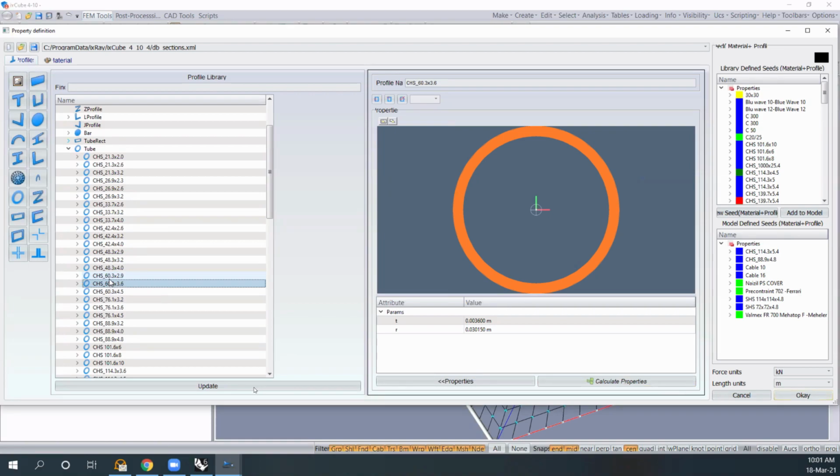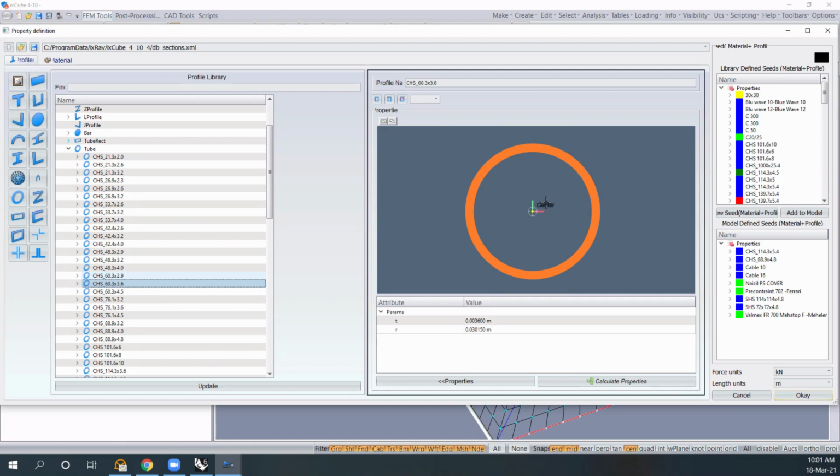when we run structural analysis on a tensile structure, generally what happens, the shape goes under large displacements. And when it goes under large displacements, it means that the direction of the connection forces is changing quite a lot. And this means that if, for example, we use as a boundary beam a rectangular profile or an E profile, it's impossible to catch the strength, the inertia in the direction that we want. I will show you better this one. Clearly, it's easier to use a circular profile if the force acting on this one changes direction. The stiffness of the profile is equal in all directions. That's the reason why you mainly see circular profiles in tensile structures.